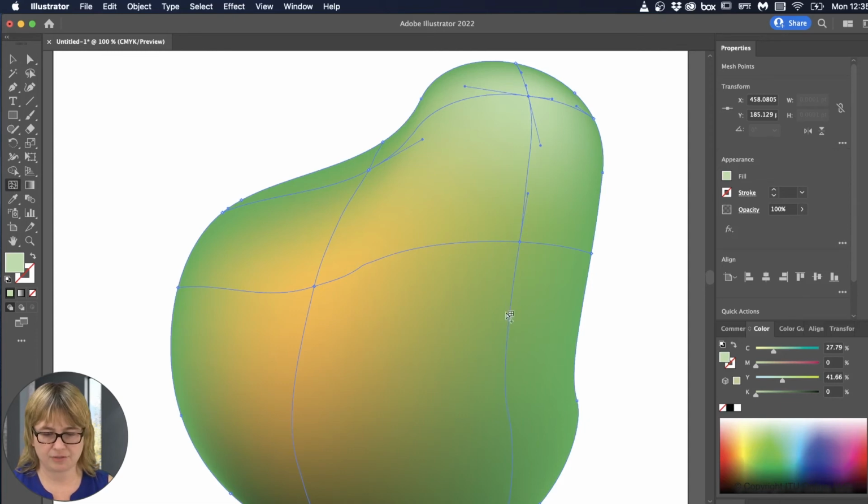Now you can also place additional curves inside. So when I had created this point, it created a curve as best it could with the information it already had. And again, yours might look different. It might even behave unexpectedly depending on how you drew your graphic. But it will intersect with the other lines. So it'll intersect with the edges that we already have around the document. It will also intersect with the other curves we've placed inside. So we have an extra point in here and an extra point in here.